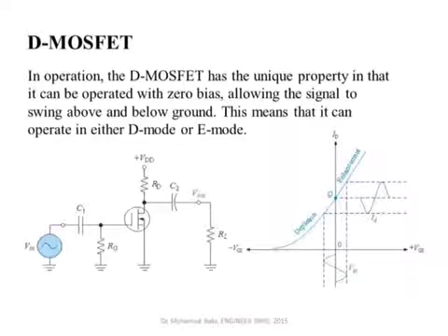We discussed in the previous lecture the common source amplifiers, and we have seen that, similar to the figure shown here, the source is either grounded or connected to a resistance that is being shorted by a parallel capacitor. This means in the AC analysis, or the small signal analysis, the AC signal is applied between the gate and the source, while the output is taken between the drain and the source. So the source is common to both the input and the output.